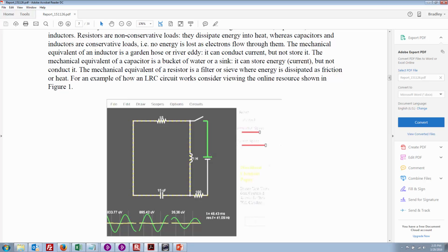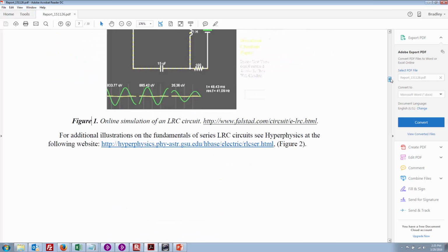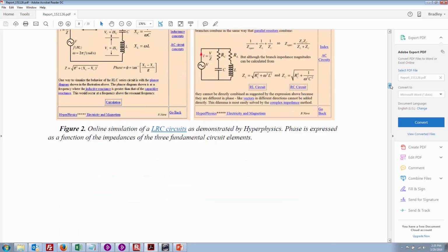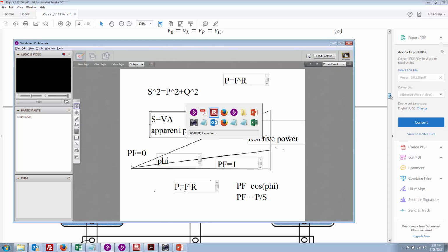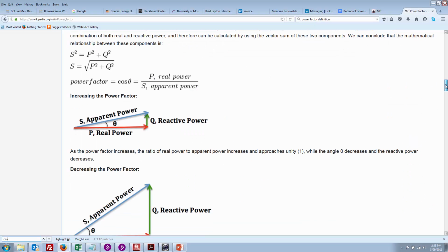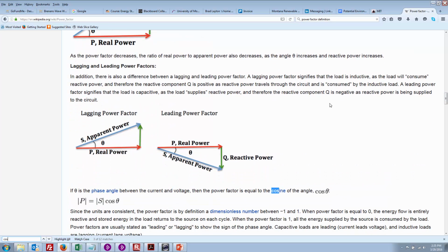If, however, you can balance an inductive load with a capacitor, then you can bring that power factor closer to unity, closer to 1. And I can show you a little bit too how there is some design work and some engineering work. You can actually overcorrect. Right, so this is the lagging power factor where the phase lags. This is the leading power factor where, well, it leads. So this would be an overcorrection or too much capacitance.